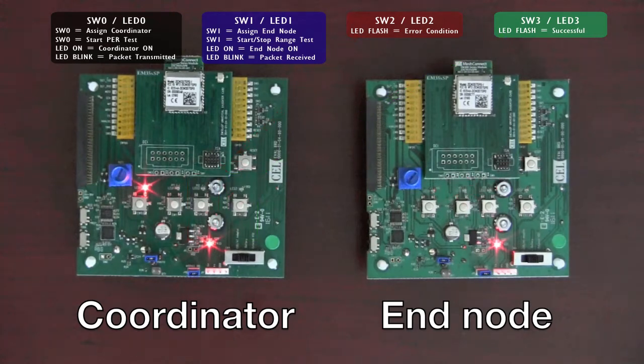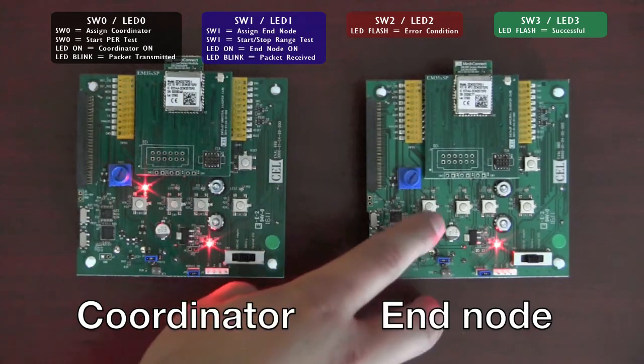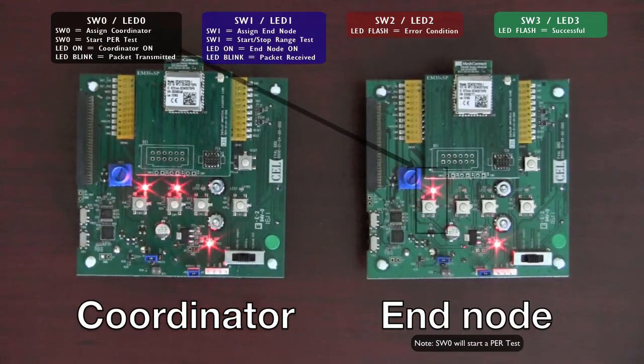You can also perform a packet error rate test from the end node to the coordinator, simply by pressing SW0 on the end node. Likewise, the end node is now transmitting 100 packets to the coordinator, and the coordinator is receiving the packets, indicated by the blinking LED lights. If all 100 packets have been received successfully, LED 3 will briefly illuminate on the end node. If there is an error condition, LED 2 will illuminate.